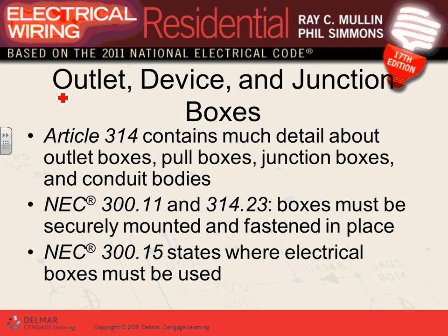Okay, outlet devices and junction boxes. All these have an article that talks about them. When it comes to the electrical devices, outlets and junction boxes, you have to put your electrical system in a box. Anybody, why can't we just splice up in the air? What's wrong with bringing two cables, splicing them with wire nuts right up in the air above the suspended ceiling?